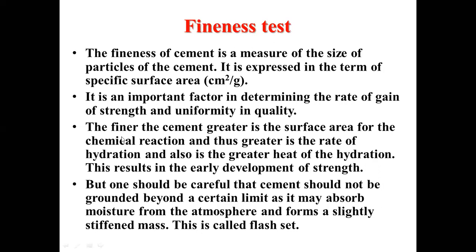The sieve test, IS 4031 Part 1, gives that fineness is measured by a 90 micron sieve. Fineness is measured by 90 microns. So it is a very simple test that we conduct.